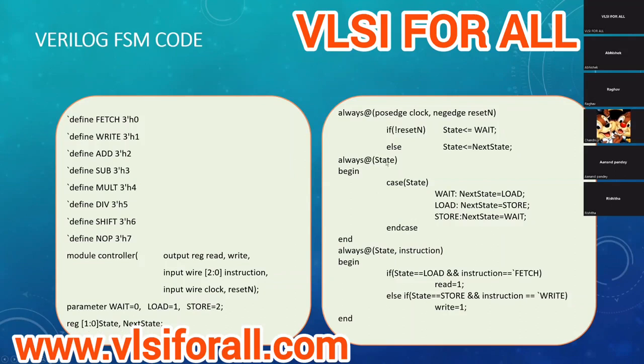This is an FSM where state is the current state and next state is the next state variable. On a posedge of the clock, state goes to the next state, and on a negedge of reset, state goes to the wait state. The wait state is basically the idle state. Otherwise, it will be in the load or store states.